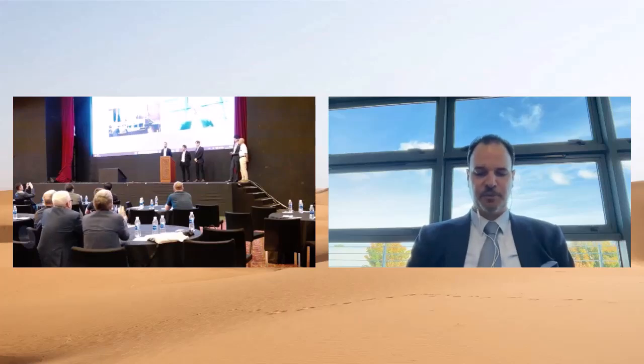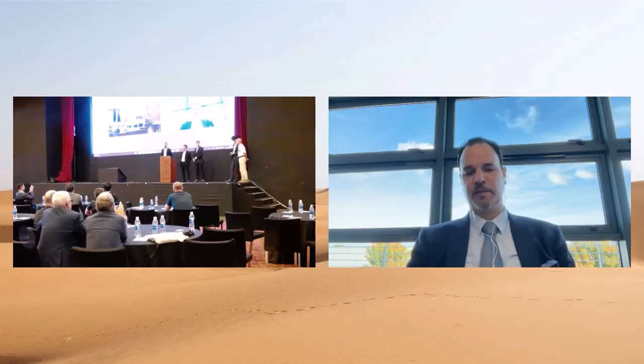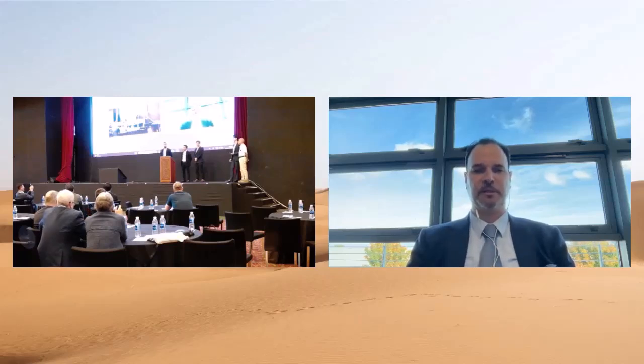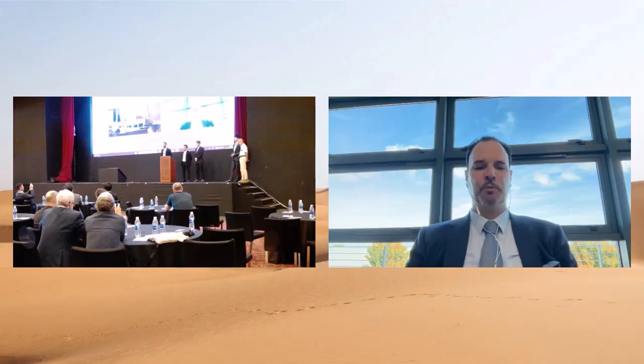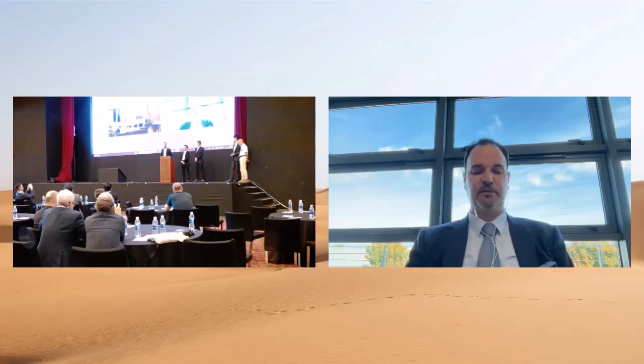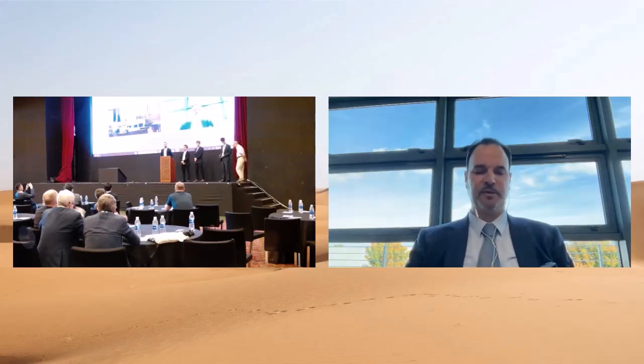Yeah, so the list of tolerances would be in your contract, depending on what the tolerance is for each discipline model, whether it's the electrical model, mechanical model, plumbing, and so forth, all have different tolerances. And even within those specifications in those contracts, the tolerances are specified differently. You can run all of the different models at those different tolerances. And to answer your question about the correction, the validation of whether something is within tolerance enough is a validation question that is answered by a human, in this case within the BCF topics that are issued.